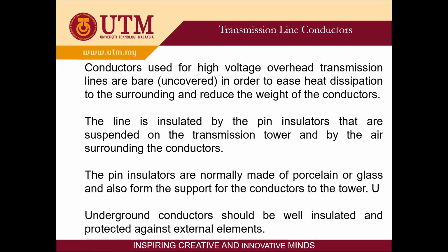Conductors used for high voltage overhead transmission line are typically bare, which is uncovered. There is no insulation. This is done to ease the heat dissipation to the surrounding and reduce the weight of the conductors. The line is only insulated by the pin insulators that are suspended on the transmission tower and by the air surrounding the conductors. The pin insulators are normally made of porcelain or glass and also form the support for the conductor to the tower.